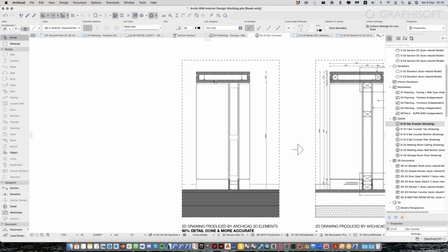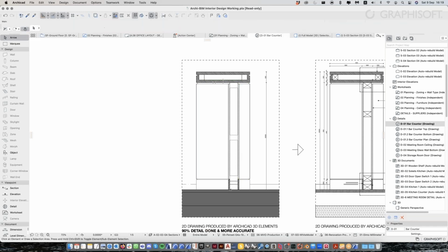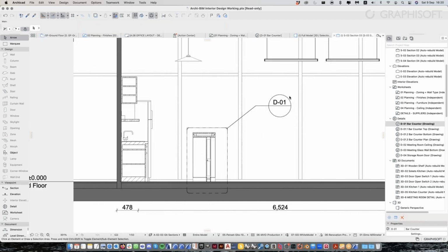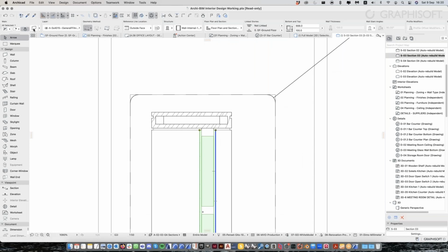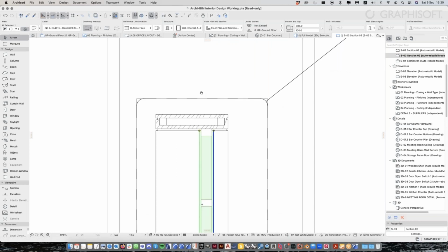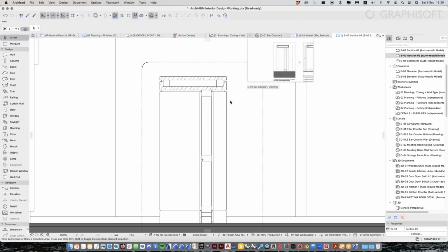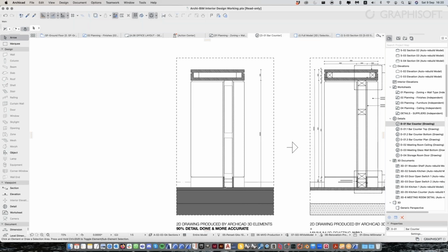So if you click on these, actually these are like 2D fills, 2D lines, etc. So it's a bit different than sections, where you can still select them as their original element type, which is the wall. It will show you that it's a wall, it's a slab, etc. So it's a bit different, in that it will convert all these elements into fills and lines.